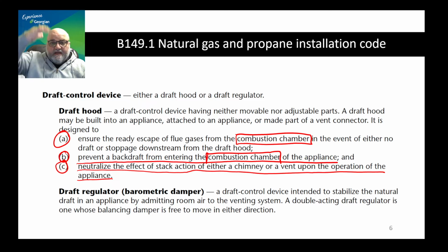And that stratification creates a pressure difference. Obviously, the pressure will be low, say in the basement of a house that is 2 stories, and it will be higher at the higher, say, second story of the house.